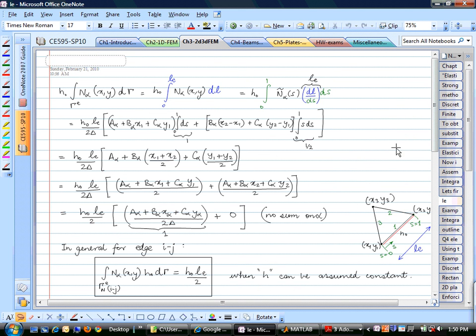In the notes, what we did was a constant body force or a constant traction on the edge. I could change that a little bit. I could give you a distribution of the body force over the domain, or I could say that the traction on this edge is not actually constant, maybe it is linear. And how does your force vector change?